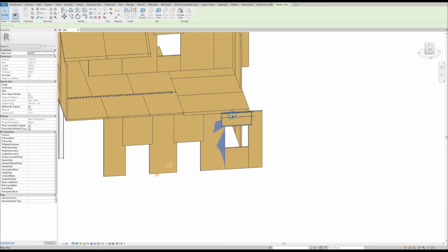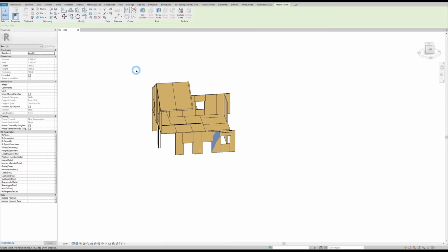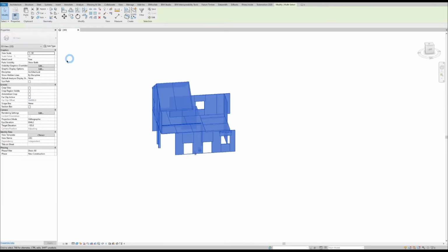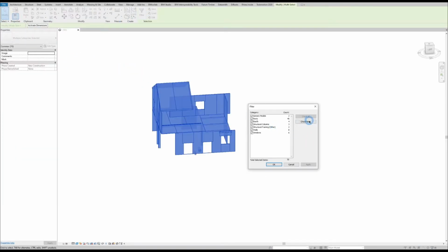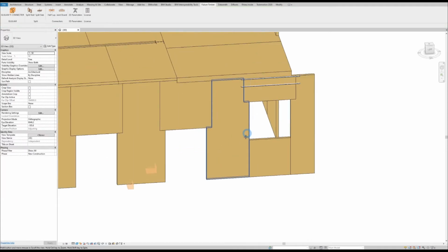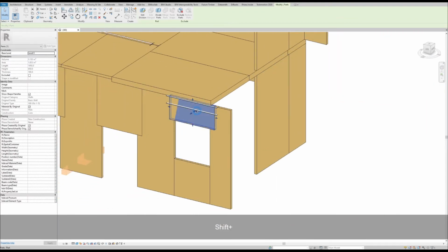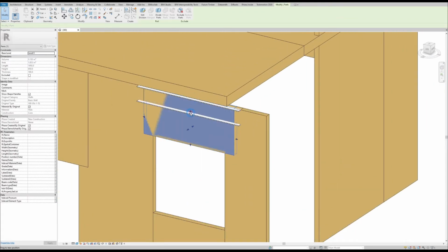We can take advantage of that to remove some portions of the panel, and we can also use a feature over here. If I just do it to all of them in one go, select only the parts, we have show shape handles, so we can tick that, and that gives us access to the panel's geometry. So we can, for example, do this over here.